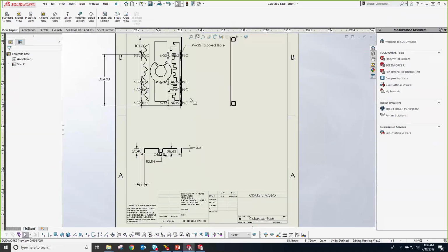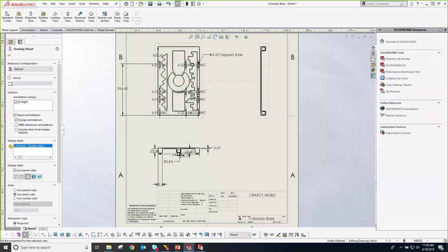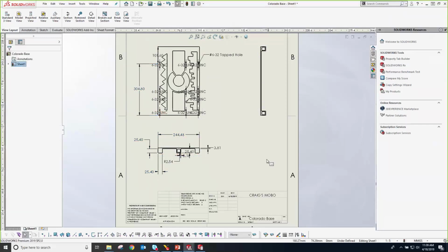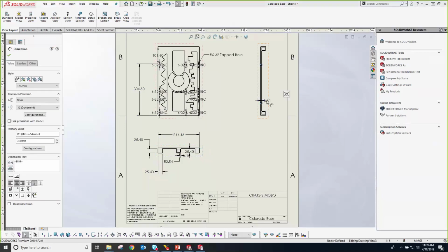And again, since I had that toggle that said open up everything, insert all of the dimensions that are created in this part, I kind of get this. Again, it's a little messy, but it's not something that I can't work with and kind of fix it, etc. Like I showed you, it doesn't take that long to move stuff around. If some of the stuff did need to be moved around, maybe this dimension into this view, you can hold the Shift key. So I'm just holding the Shift key, dragging and dropping into this view, and you can see that I have physically moved this over here.